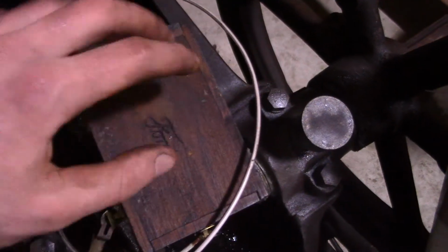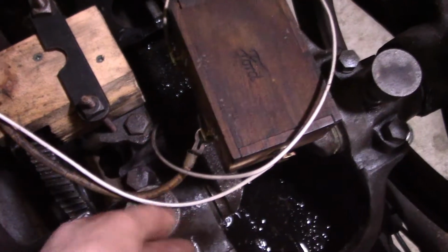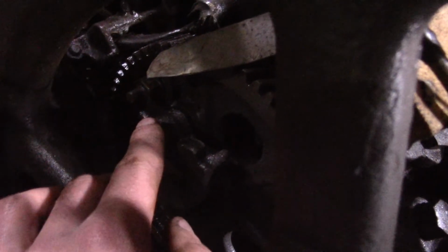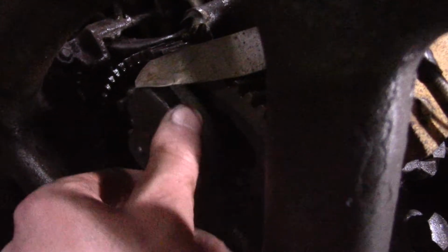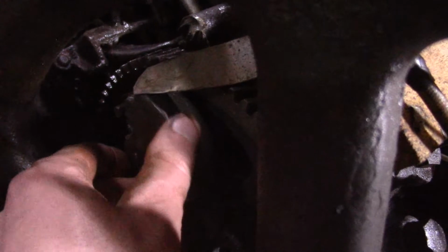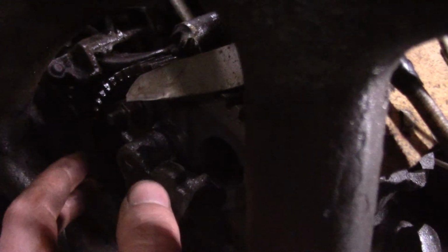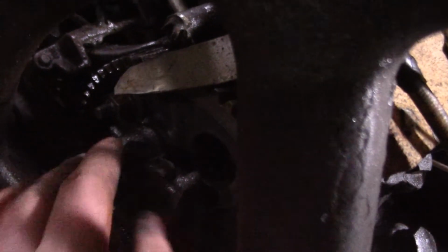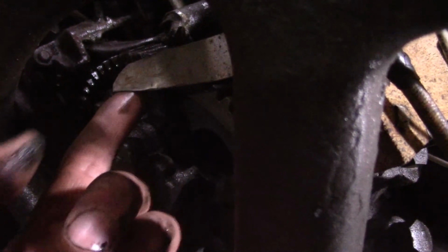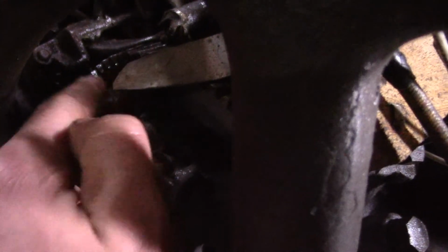The way this works, or at least on this setup here, ground is just ground, of course. I made a trip. This is just a piece of metal, and as this flyweight comes around, this flyweight is actually the advance and retard function for the original magneto. As this comes around, it touches this little wiper here, and it makes and breaks contact.